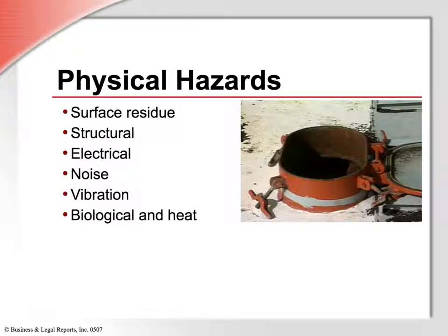There are also physical hazards. Surface residue can increase the hazardous conditions of electrical shock, reaction of incompatible materials, liberation of toxic substances, and body injury due to slips and falls. Structural hazards such as baffles and horizontal tanks, trays and vertical towers, bends in tunnels, scaffolding, or overhead structural members are hazards exacerbated by physical surroundings. Do not introduce electrical hazards such as lights or equipment. They can cause explosions, so use explosion-proof lights.